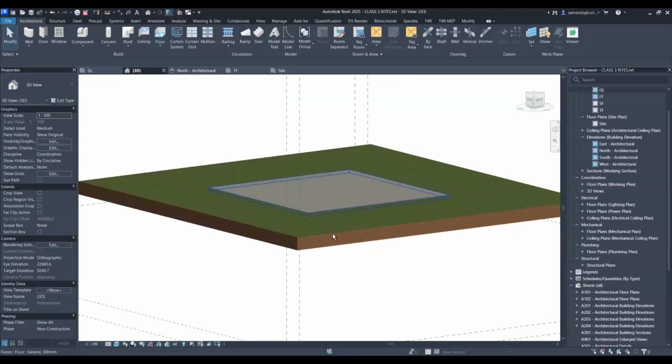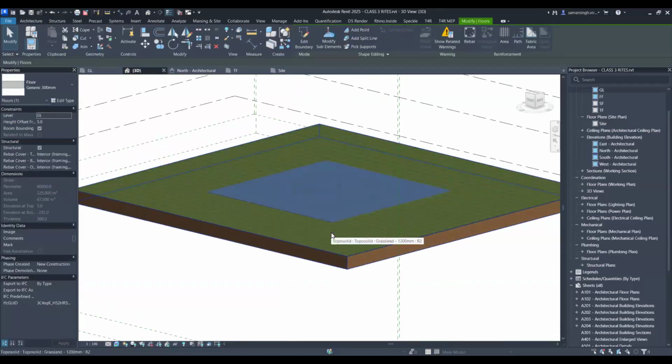So this is what I'm telling right now. This does not relate to just this specific floor wall. This relates to everything in Revit. So you might face a clash like this between maybe a column and a wall, a wall and a wall, two floors, or anything like that.